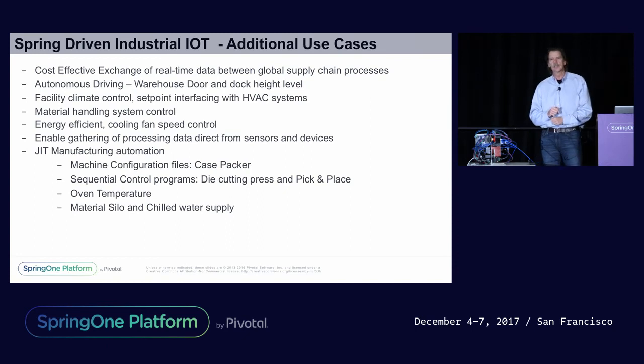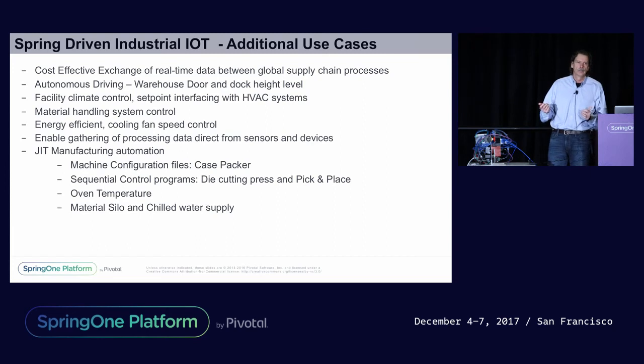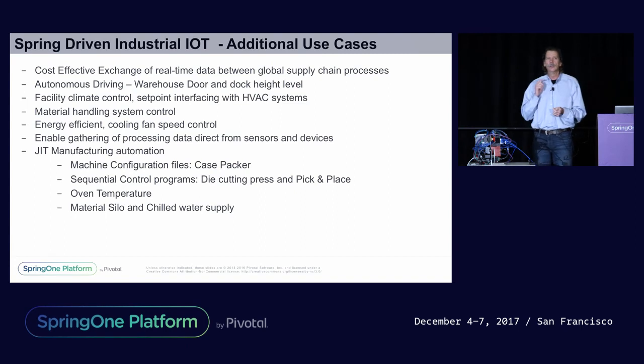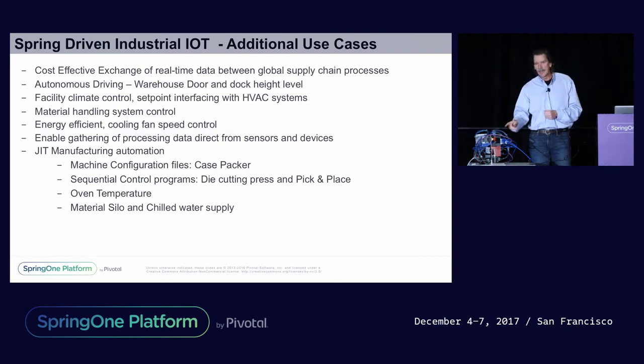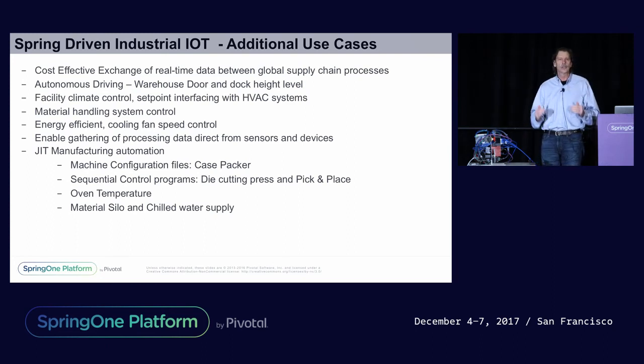So when they put those harnesses in that oven, what happens if the line goes down? Those bags can stay in there too long and overheat. So the enterprise knows that when the line's running, it knows what the production rate's going to be. So by using a gateway, the enterprise can send down to the oven, and you can adjust the temperature up and down on the oven based on the dwell time that this bag's going to be in there, so you don't overheat these bags.